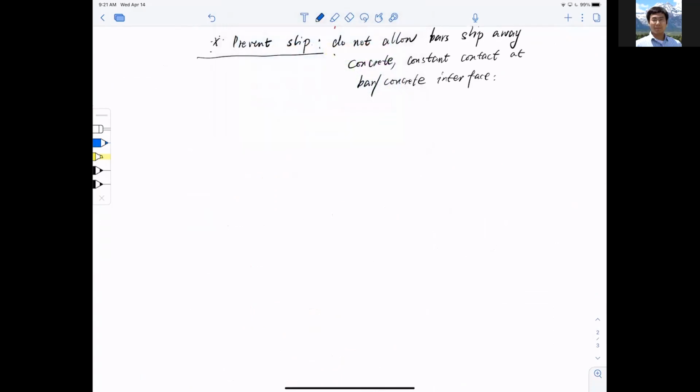So in this scenario, I have a beam or column joint, and I have a tension bar. Since it is a cantilever, I'm going to put my bar on the top, and assume it's a straight bar. All I need is to calculate this development length, which is how much bar has to be embedded inside the column. So how do I calculate that?